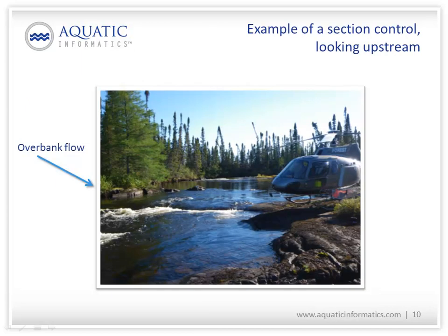When we're doing site reconnaissance, we're always looking for a level pool with the discharge controlled by a natural section control feature like a rock ledge. So this location looks promising. I'd be a little bit concerned about the velocity approaching that rock ledge. I'd also be more than a little bit concerned about the shallow banks and the complex geometry and what that's going to look like at high water. So if I was doing this site reconnaissance, I might want to keep looking. However, it might be the best we can find on this stream.